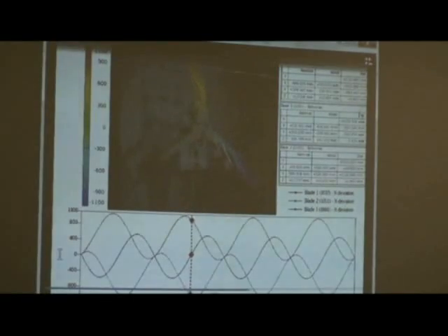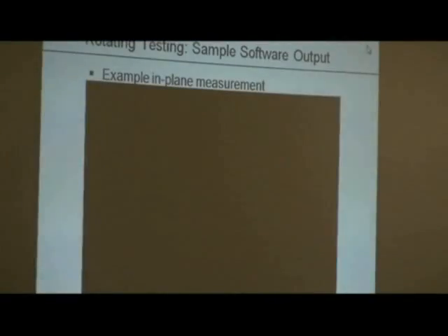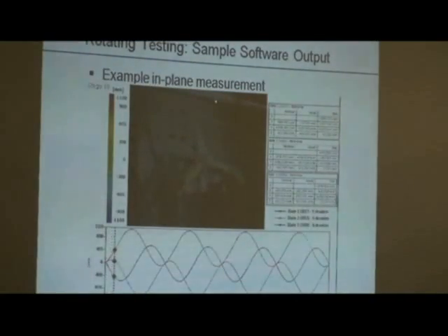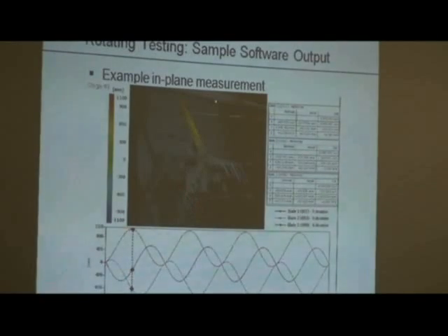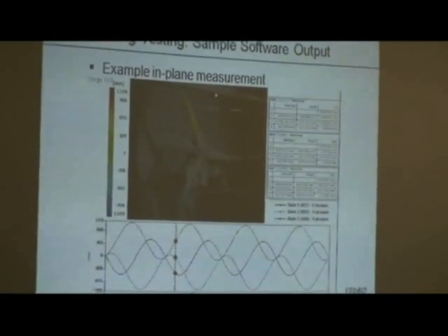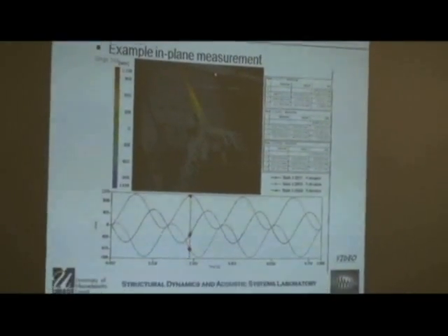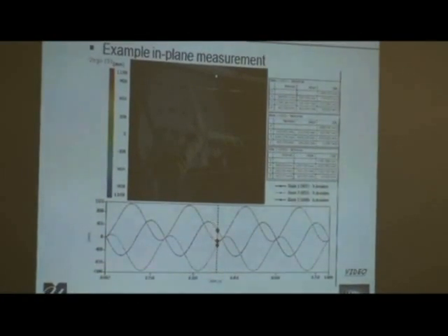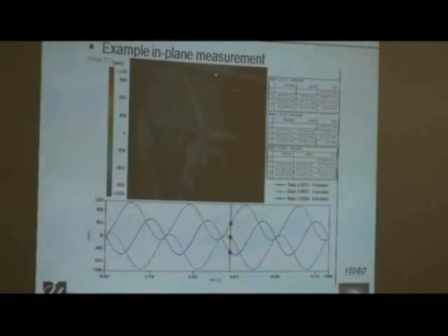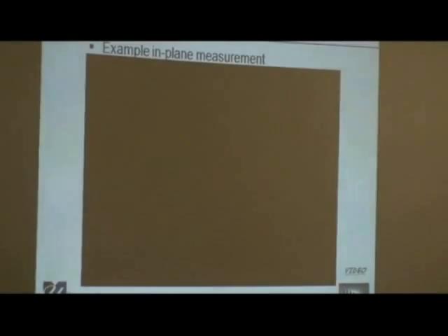We can also look at the derotated view. No, that's the same thing. All right, this is the same thing, except we're using arrows to indicate the motion. This is again the in-plane motion of that wind turbine as it's rotating around. Physically, if it's moving in a circular motion and I'm looking at a component of it, I would expect sinusoids, and that's what it is. So I'm getting confidence that this technique works. But for vibration, we're more interested in the out-of-plane motion.